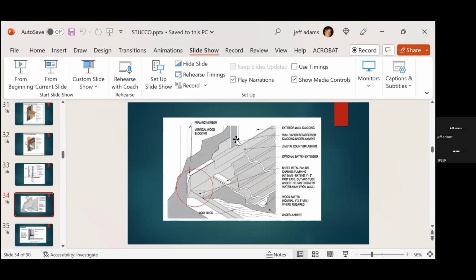Another roof detail, and this one works here too as well, and I like this one. So we have our base flashing using our counter flashing. Our counter flashing can work as long as we go up 3.5 inches, okay, from this inside corner up, because it does spell out 3.5 inches. It's got to go up. It does have to go on behind our WRB here, okay, for this. But the only thing about this is this does have to be at a slight angle here so the water can drip out of this edge here. Okay, so it does need to have a slight angle on there in order to work. Okay, and if it's not done like that, it can trap moisture in there.